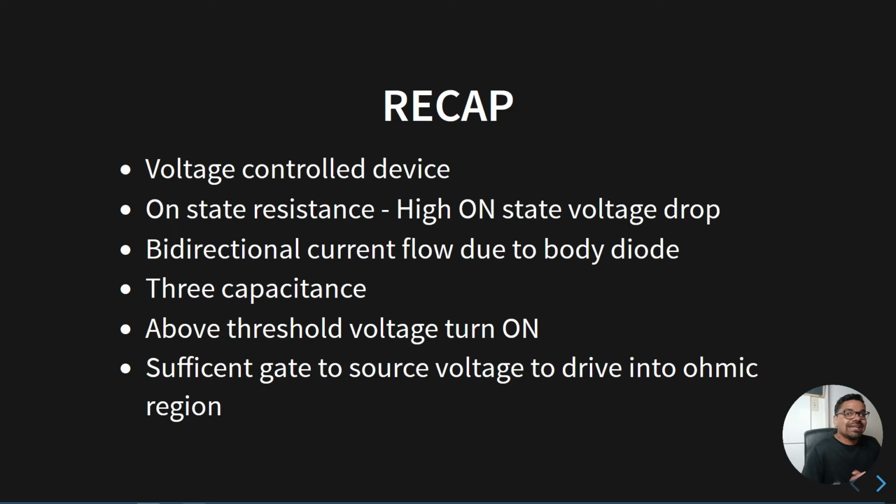In the next part, we're going to talk more about the switching characteristics of a MOSFET and how this is also important. In the switching characteristics of the MOSFET, we're talking about the transient conditions. When you're switching, how does your MOSFET go from 0 volts all the way to, say, 5 volts or 10 volts, 30 volts, based on certain inputs? And is it going instantaneously? No, it's not. There is some form of rise time. There's some form of fall time.